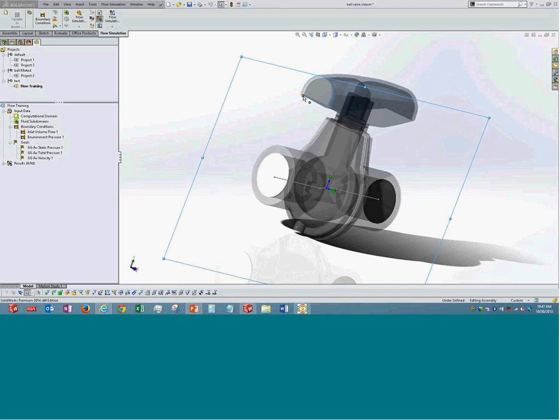If we don't know the outlet conditions and we are expecting the fluid to go into an atmospheric condition, or it's a huge pipe on which it is out, then keep it at environmental pressure, and the software can calculate the static pressures for you, or the absolute values of pressure, then definitely use the static option. And that is more advisable, no doubt on that side.